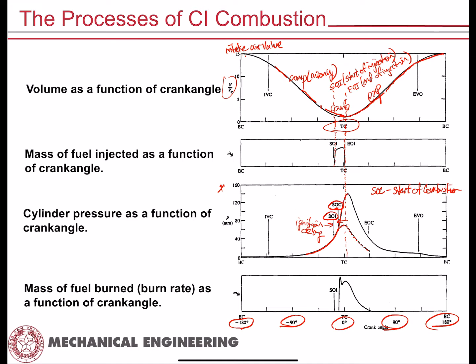It reaches its peak, and then begins to fall as combustion starts to die down, and the piston is now rapidly expanding that volume. Eventually, I come to EOC, or end of combustion. My piston continues to expand that mixture, and then eventually I get to EVO, exhaust valve opening, and everything is done. Okay, so that's the processes of compression, ignition, combustion.